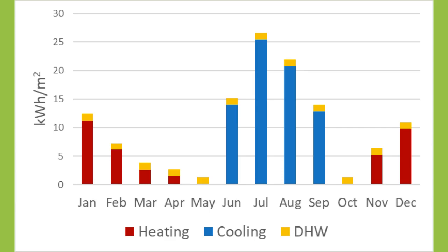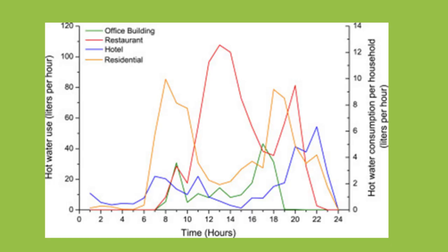Therefore, monthly thermal demand for space heating or cooling will change depending on these conditions. Changes in domestic hot water can remain almost constant over the year. And regarding hourly consumption, it additionally depends on the utilization of the building during the day for both space heating and domestic hot water. From these data, peaks and daily demand are used to size boilers and storage systems.